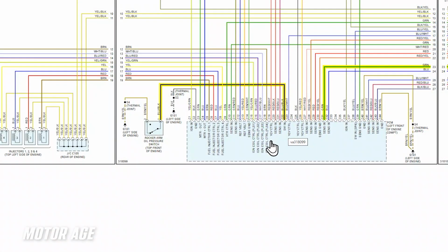But at the same time, that same hydraulic oil pressure acts upon a switch. And what we learned from referencing the wiring diagrams is that the switch is a normally closed switch, meaning under, I'll call it normal, low-end engine operations, the switch is closed, and when that switch is closed, a voltage reference leaving the PCM references ground and is pulled low.